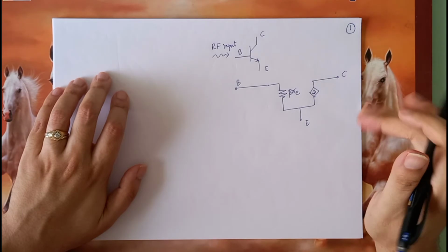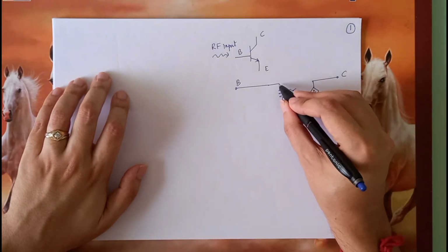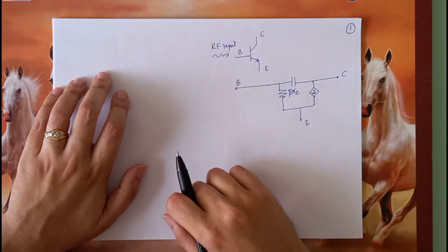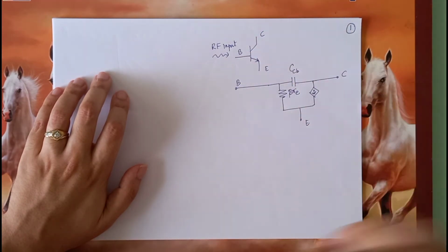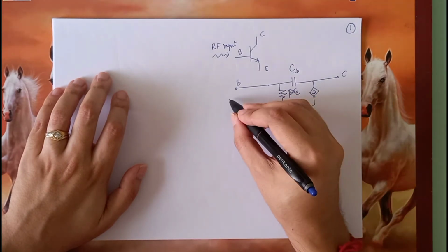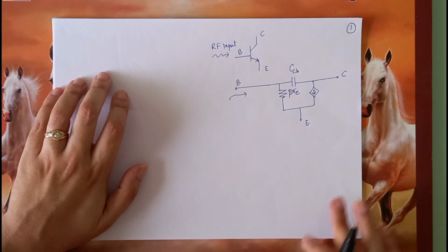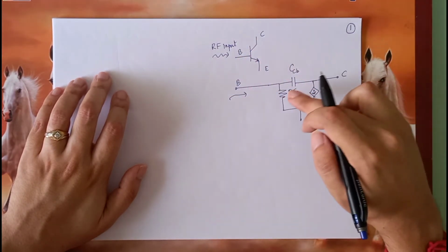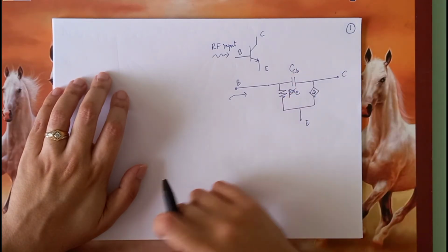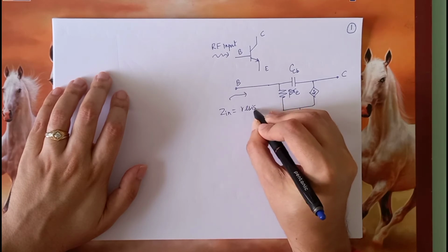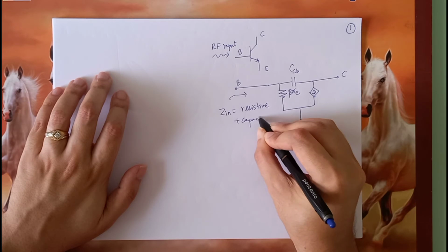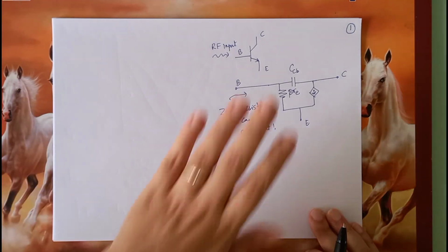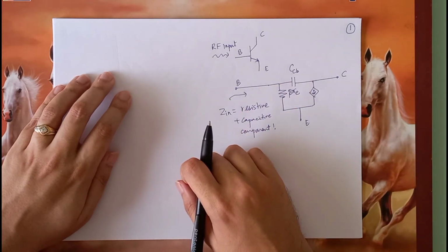As you know, the collector base junction is reverse biased in a BJT amplifier. So there will definitely be some capacitance seen in the reverse bias because of the depletion region between the collector and the base. This is called CCB. Now if I am looking into this base, and the emitter is at AC ground, the input impedance looking into the base of this transistor will be some combination of resistive and capacitive. Therefore the impedance of this device in general will be complex.